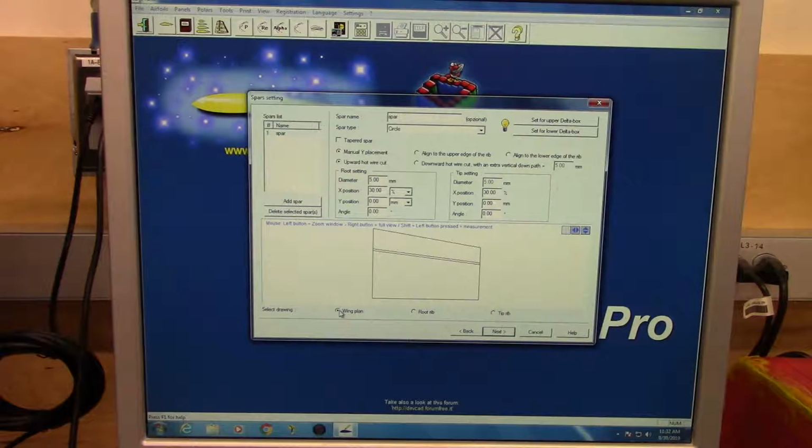And under wing plan, I'll come back and say, okay, again, I want this to be straight. So I'm going to determine this based on, I've done the math beforehand. I'm going to say my X position, my distance down my chord, is going to be in millimeters instead. And if my X position is at 45, I like that because that's the thickest point of my airfoil for the smallest airfoil for my panel. I'm going to come back to my root and actually move this back to a distance of 95.